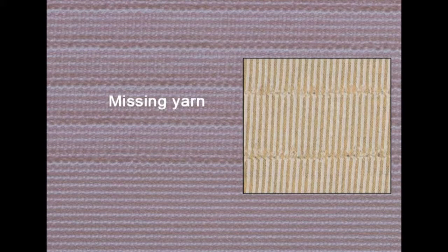And in the case of missing yarn, that occurs in circular knits, caused by one end of yarn missing from the feed and the machine continuing to run. In woven fabrics, it is a yarn absent from a pattern, and sometimes it is treated as minor or major. And we have even fabrics coming out with missed picks also, in the form of systematic patterns.